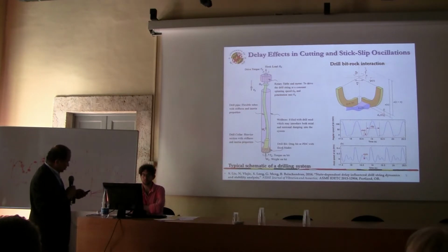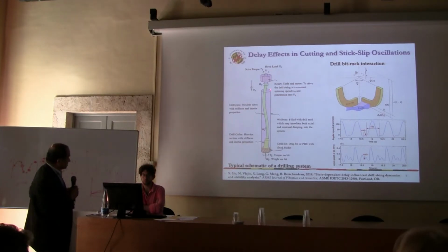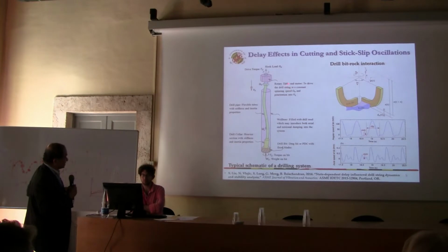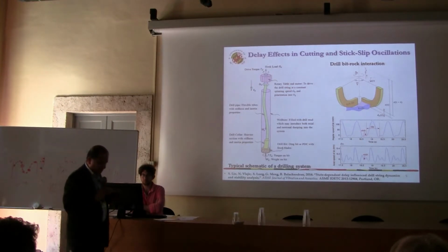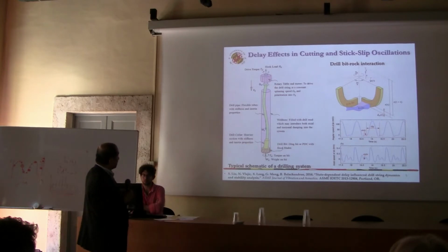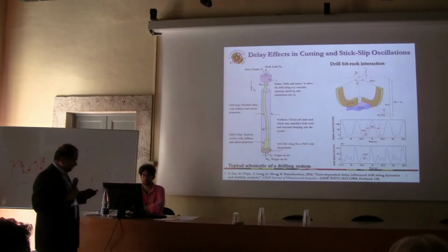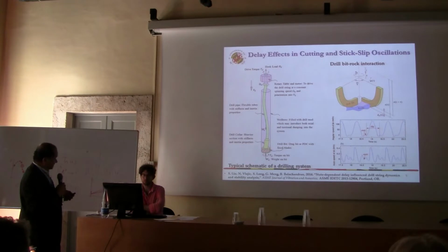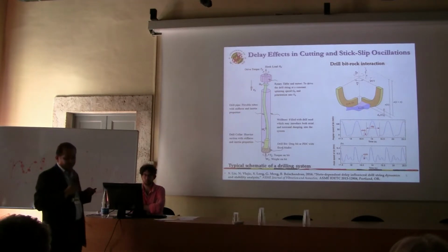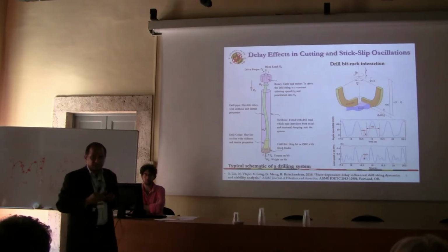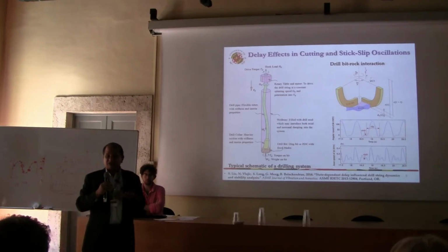But for this case, the drill string is several kilometers long, and the drill collar, which is a heavier section, is about 100 to 200 meters long. The two control inputs for us, for bifurcation purposes, are the drive torque, the RPM that you put on the system up on the top, and the penetration speed V naught. So these are the two control parameters that you'll see me referring to as we go forward, in terms of how they affect the stability of the system.